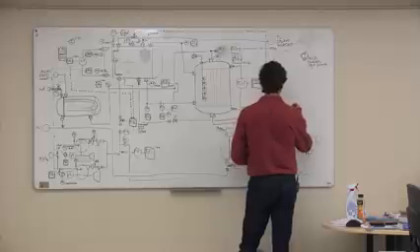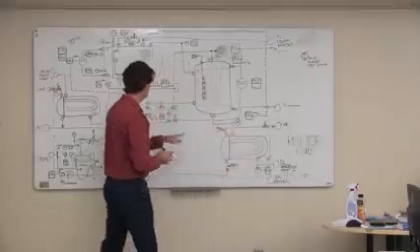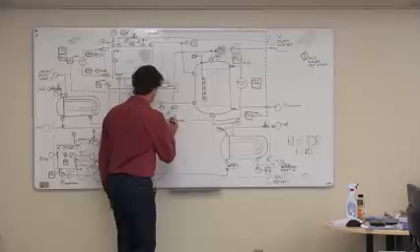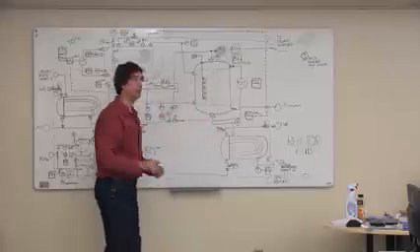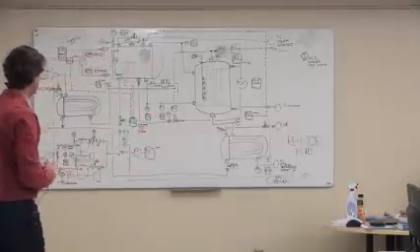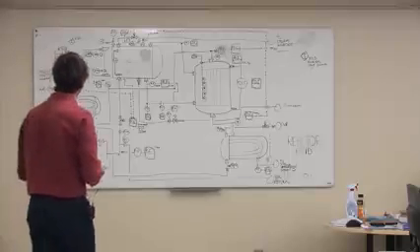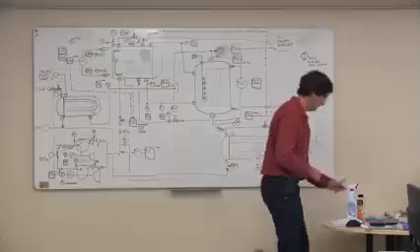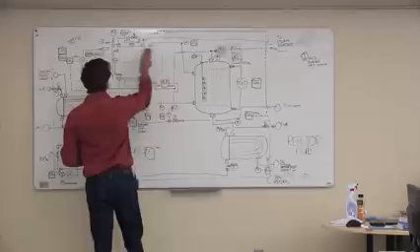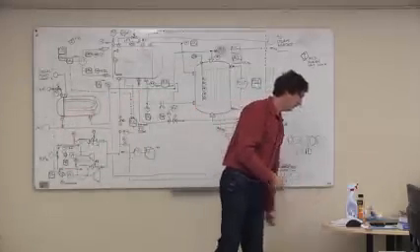It's called blowdown. The only problem is there's quite a bit of heat in that water, so if you start to get clever, you might want to put a heat exchanger on there and maybe preheat water with it, because that's one of the energy losses in a system like this. Do we miss anything else? I think that's probably it.